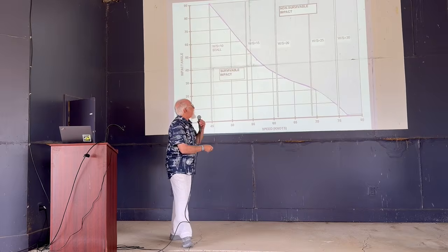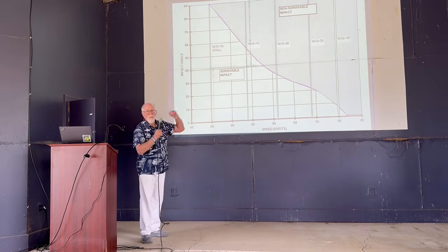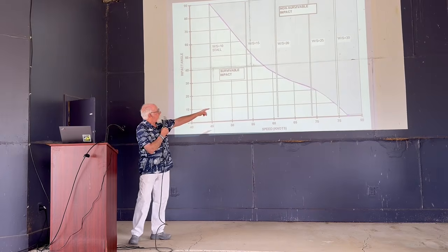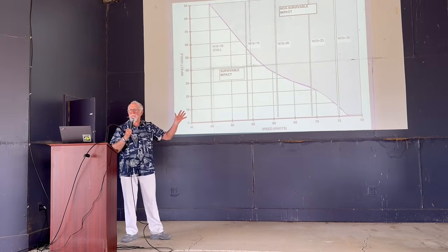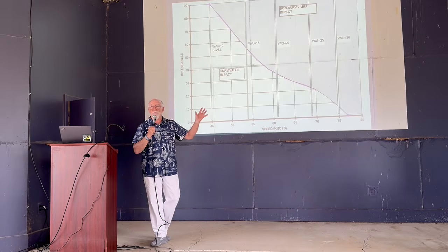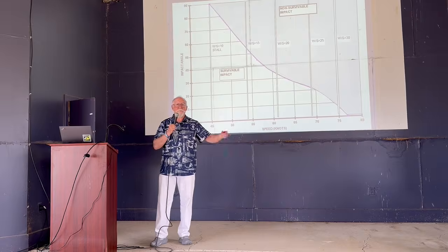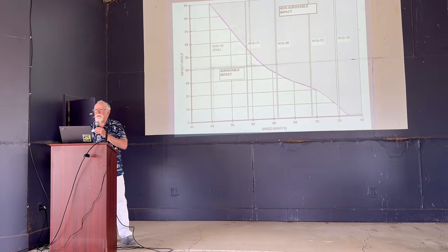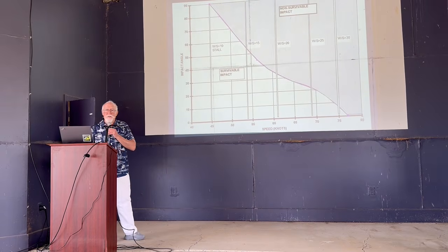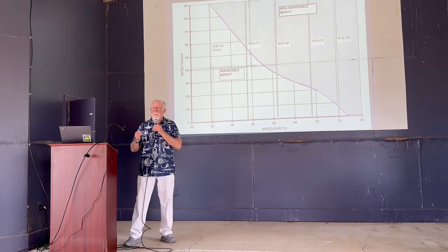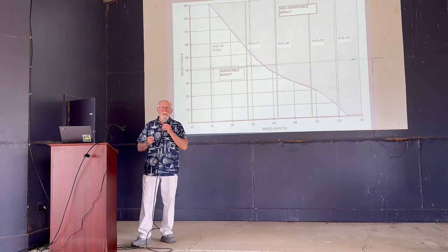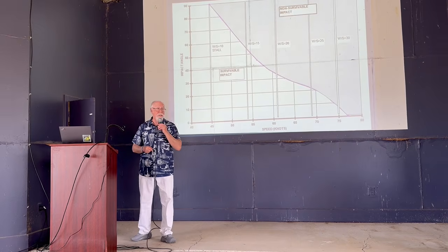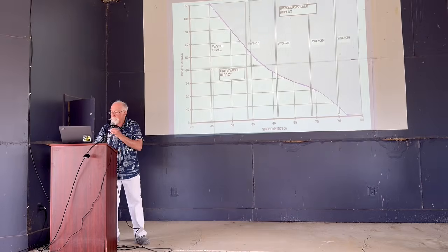Now, what I've done here is put lines of constant wing loading with approximately the stall speed. So this is why you say, okay, I don't want to get much above 20 to 25 pounds per square foot wing loading in a light airplane for survivability. And that's for that dead stick impact with the ground. So if you're taking off in your very high performance, high wing loading composite airplane, you want a very, very reliable engine because you're going to have to find someplace smooth to land on actual landing gear if you have an issue.